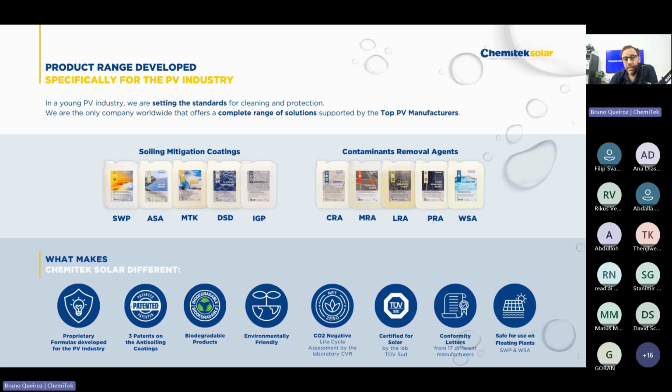The other type of coatings that we have are the hydrophobic coatings that we recommend for rainy areas where there is constant presence of water on the panels, like tropical areas, Northern Europe, where it rains a lot and where the water repellency of the coating can help keep the panels cleaner by creating bigger droplets and making them remove more dust as they fall down the panel.